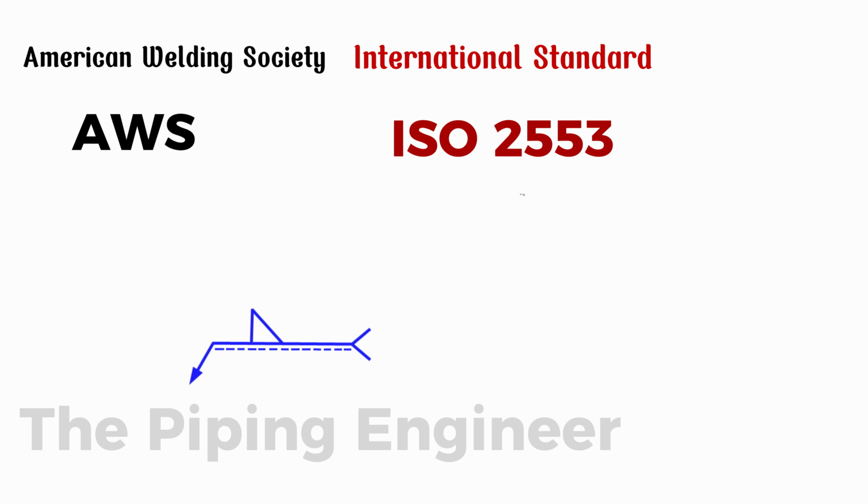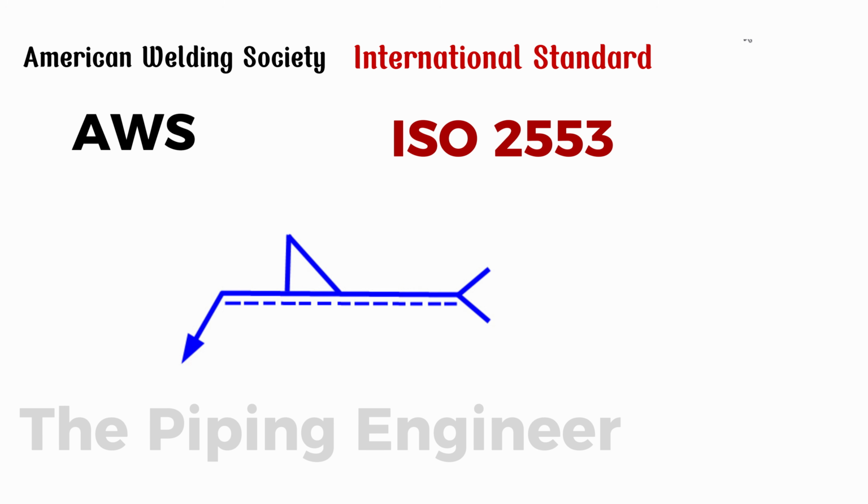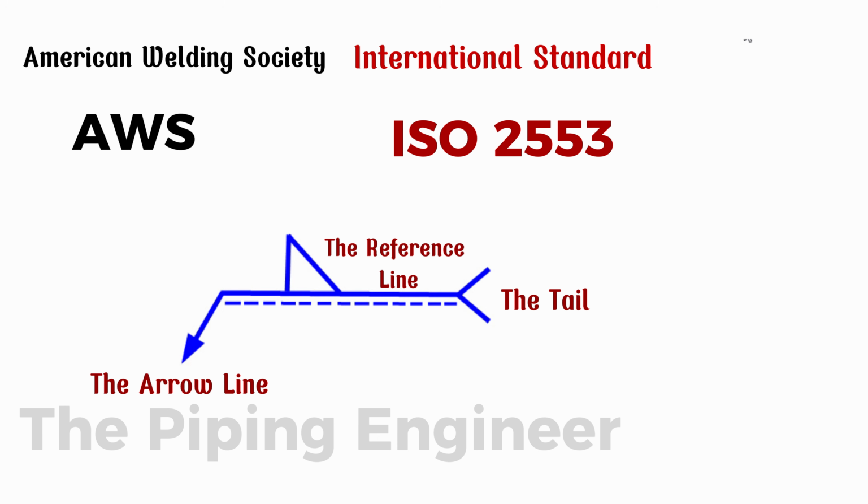No matter which standard you're using, every basic welding symbol consists of three core components. 1. The arrow line points directly to the joint where the weld needs to be made. 2. The reference line, the horizontal line where all symbols, dimensions, and instructions are placed. 3. The tail, the optional end piece used to show specific welding processes or WPS numbers.